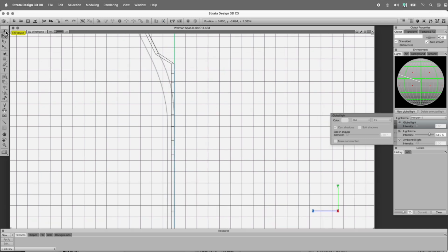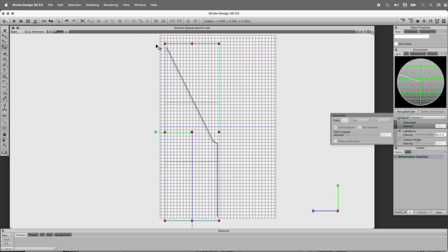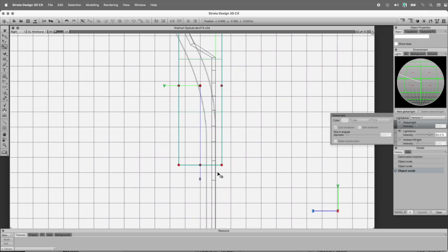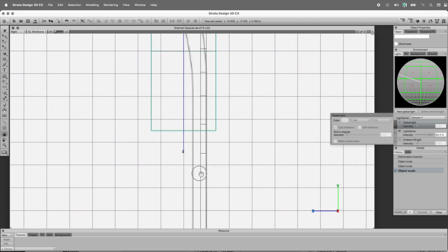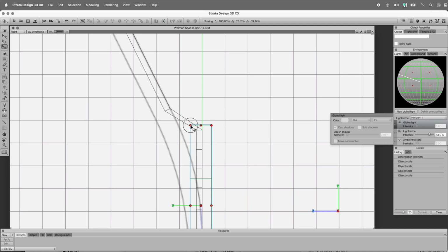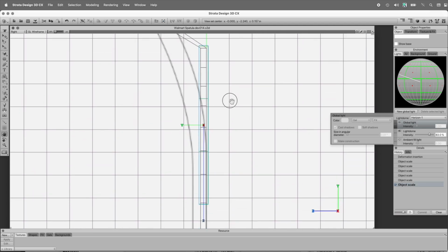Let's leave edit mode and we're going to come over to the deform tool and click that and set it so it's 4 by 2 by 4. Click OK, and then click on this object. By default, it's going to conform itself entirely to the entire shape, but we're going to restrict it to just this area that we want to work on. So we want to leave this alone here. So we'll just come right to the bottom of that. And then here, we're going to encompass just these parts of the geometry that are going to deform.